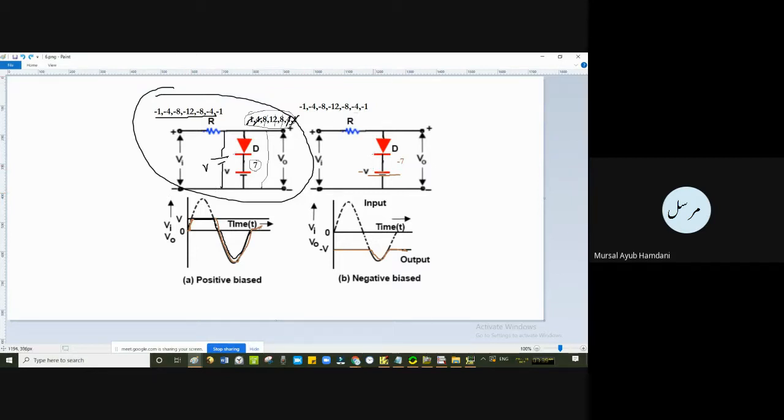Accordingly you can then make different circuits by assuming these things. So it is clear that in the shunt case, output will follow the input when the diode is open circuit, while in the series case, the output will follow the input when the diode is closed circuit, forward biased. So here reverse bias is a good thing for the output to follow the input. So these are the series and the shunt type of clipper circuits, with different examples and different directions of the diode.